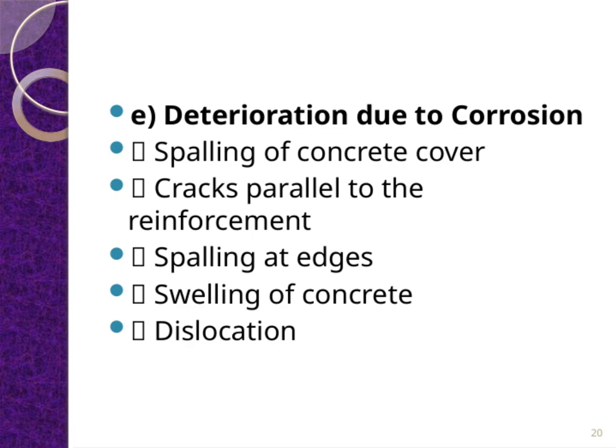Another key point is swelling of the concrete, which is a result of the corrosion process causing expansion inside the material. This swelling can lead to dislocation, or movement, of the concrete and reinforcement. Recognizing these signs early is crucial because they directly impact the structural integrity and safety of the structure. Corrosion-induced deterioration is a major concern in maintaining the durability of concrete structures over time.